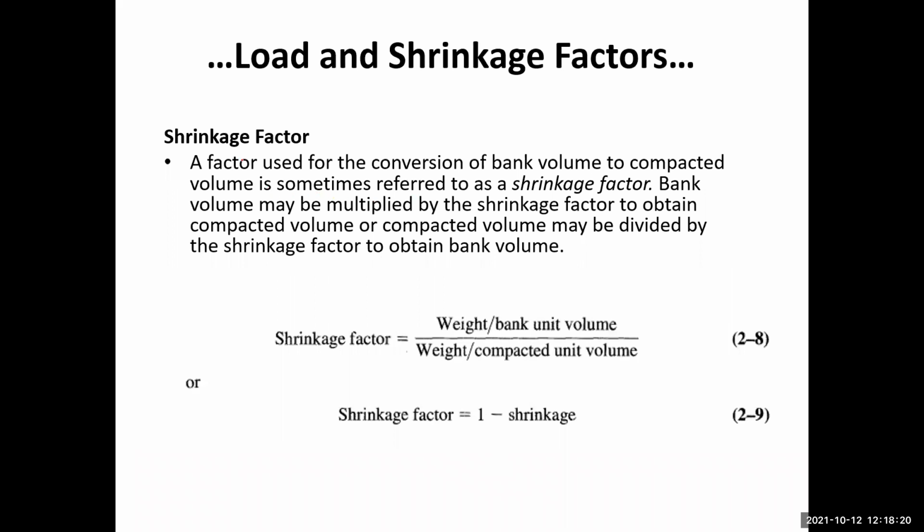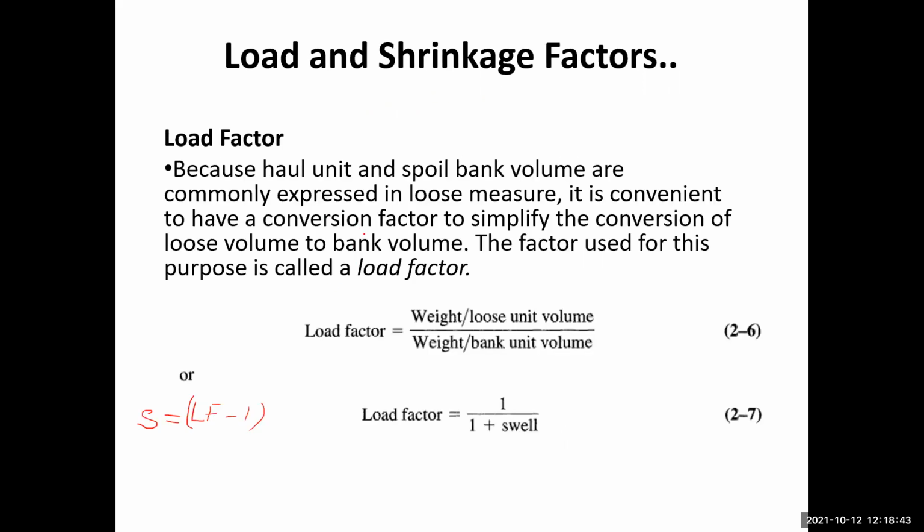On the other hand, we have the shrinkage factor, a factor used for the conversion of the bank volume to the compacted volume, sometimes referred to as the shrinkage factor. So bank to compacted, okay, shrinkage factor.